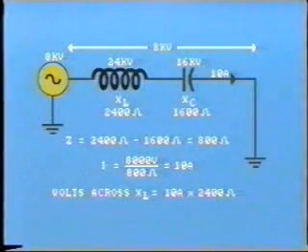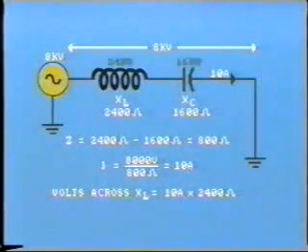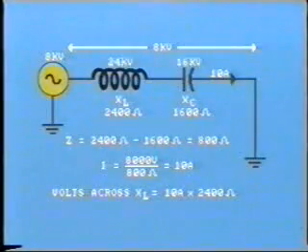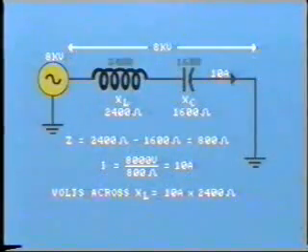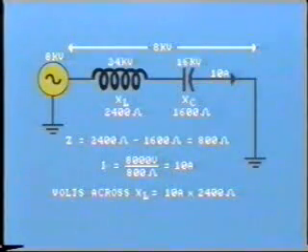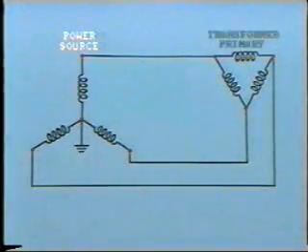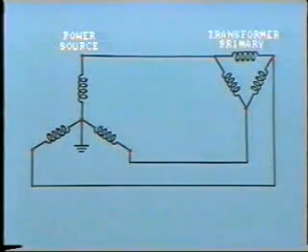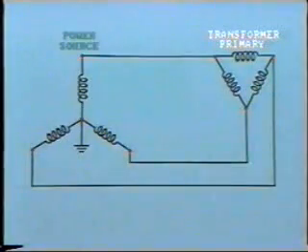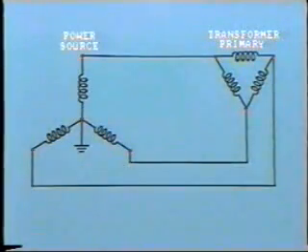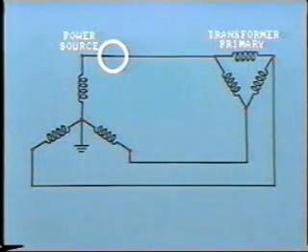So although only 8 kV is applied across the total circuit, we have very high voltages in individual parts of the circuit. And this is precisely what happens when we have ferroresonance in the power system. Typically, this can occur where we have a delta-connected primary of a distribution transformer. In this system, the distribution line is being fed from a Y-connected secondary with the neutral grounded. As this is a distribution line, fuses are often used, so let's consider the situation where one fuse only blows, such that we have one phase open-circuited.